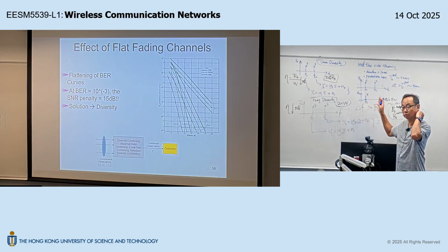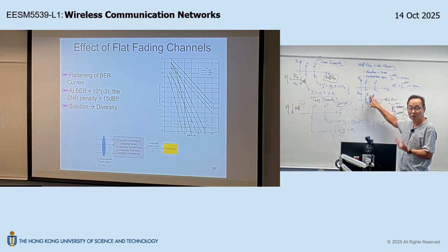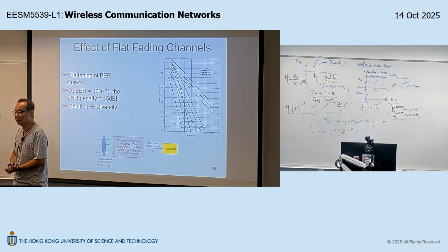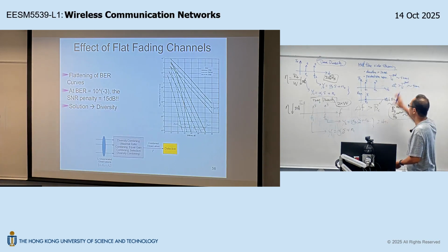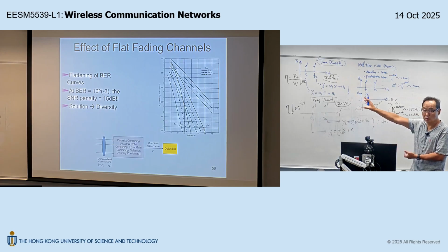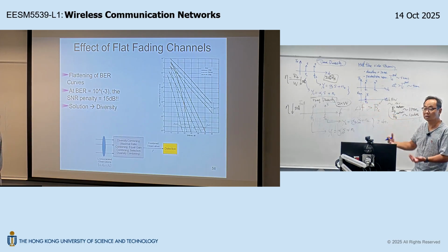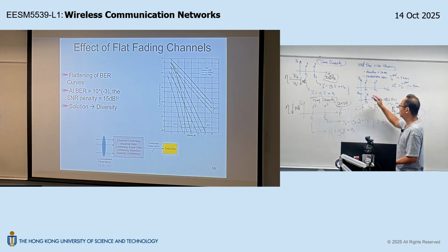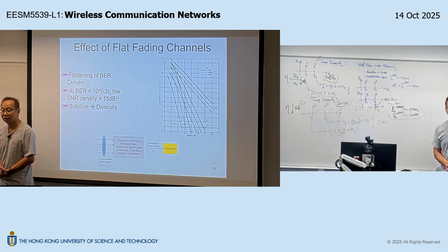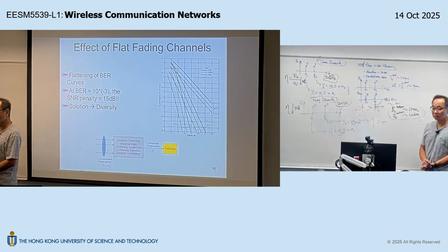No, right? Because if you start demodulation, you are only making use of 1 observation. You are not making use of 2 observations. That means you are not utilizing diversity, right? To utilize diversity, you need to make use of these 2 diversity observations before making a decision. So you need to wait for Y2 to arrive. Only at this point can you start the demodulation, right?